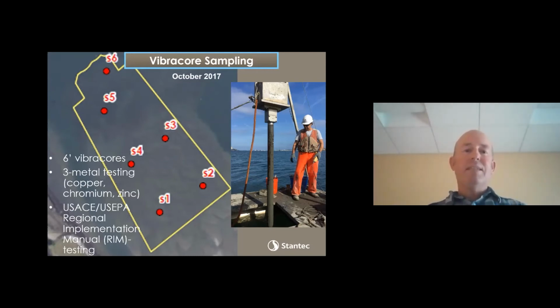What we found out here is that at our site, the surface sediments are relatively clean. And once you get into marine clay, the copper, chromium, zinc levels actually tick up a little bit, which was news to us, but looking at the literature, that is a feature of marine clays. The province of Quebec actually has separate sediment screening guidelines for their marine soils or marine sediments because of this feature. So lesson learned: the 3-metal test does not work all that well when you're in marine clay sediment.